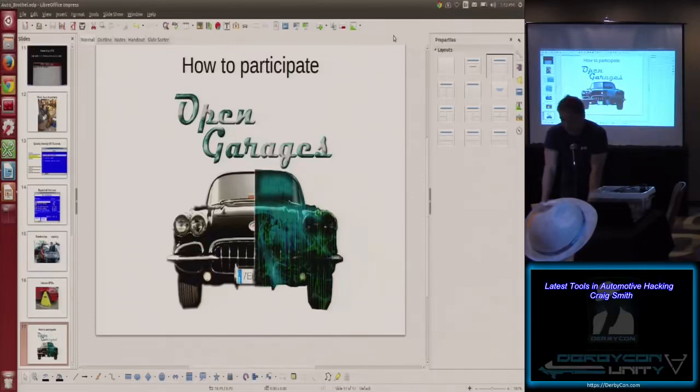And so then you send a packet that tells the ECU to reboot, like, oh, you should reboot. And then when it does that, you can do it again. So the tool just does that. It waits for an error and goes, you should reboot. And then we continue where we left off. It's not too hard to write. I think it's around 200 lines. That's one way to get that key.